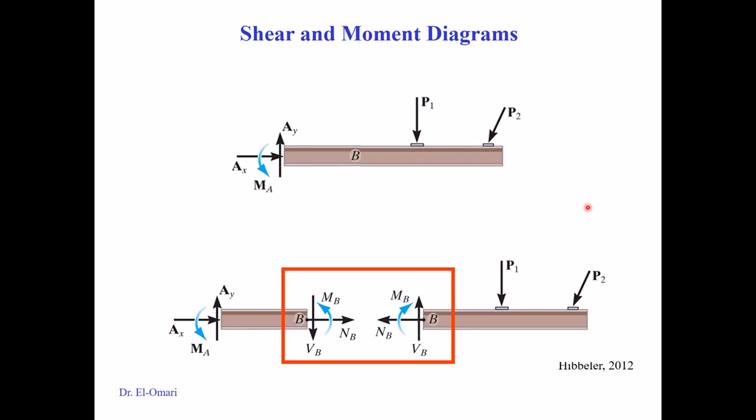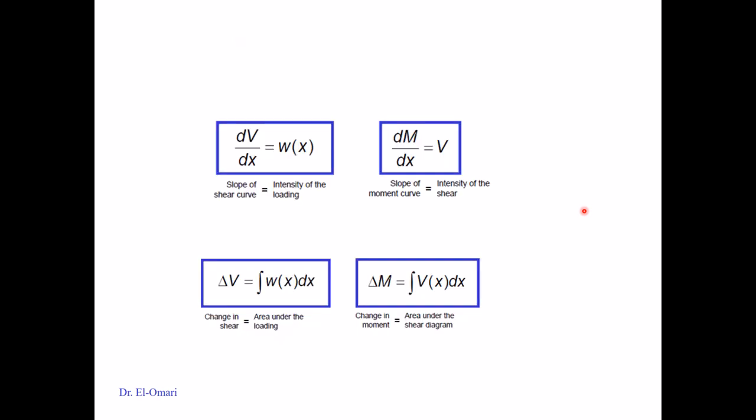To continue, a most important note is the relation between the load, the shear, and the moment. It is an integration relation. If you integrate the load once, you get the shear, and if you integrate the shear once, you get the moment. This also gives us a lot of information about the shape of the line.